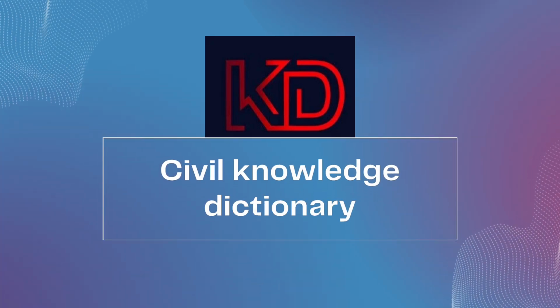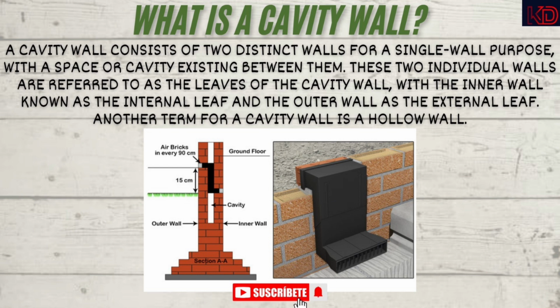So I again brought one good topic for you guys. That is, what is a cavity wall? Basically, a cavity wall is a wall which consists of two distinct walls for a single wall purpose, with a space or cavity existing between them. These two individual walls are referred to as the leaves of the cavity wall, with the inner wall known as the internal leaf and the outer wall as the external leaf. Another term for a cavity wall is a hollow wall. So you can also call it a hollow wall.